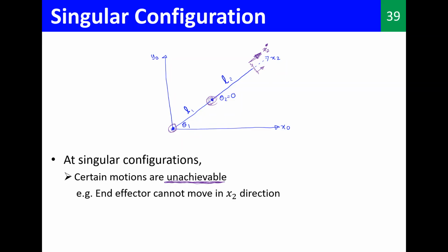We will talk about these later in greater detail because they are very important. Let's say we built a manipulator and sometimes we pass through a singular point, then everything goes to chaos. It can get stuck and we don't know what to do after that. It gets stuck because the calculation of the motor velocities that we should give produces a very undesirable infinite answer. Things like that can happen. We will talk about these singularities later, but here I'm just giving you the outline of what to expect in the future. All of these are very important.